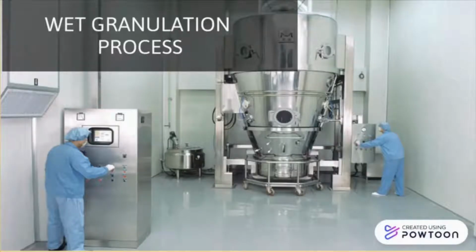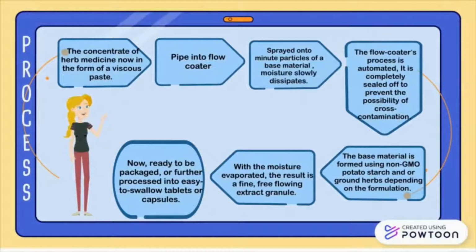Wet granulation process. The concentrate of herb medicine, now in the form of a viscous paste, will be piped into flow coater. Next, the paste is sprayed onto minute particles of a base material. The moisture slowly dissipates. The flow coater's process is automated. It is completely sealed off to prevent the possibility of cross-contamination.